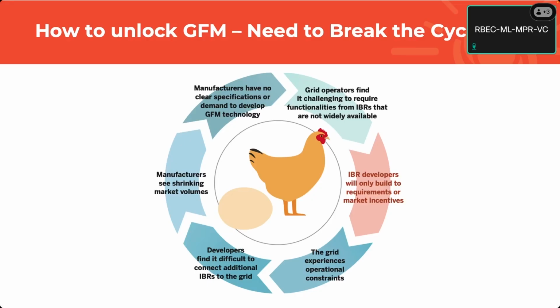Yeah. I think if you just have a regular inverter with a DC bus, there's no inherent problem with a grid forming control for the DC bus compared to grid following. It's going to be a current issue on the battery. You're not really cycling state of charge on a full battery. You're just moving the current in and out in a little bit different way. I'm told that it's not a problem for the batteries, but when you have a DC coupled hybrid system, now you have two different sources of current. That seems to be more challenging for DC control. I'm not sure exactly what the challenges are for them, but for some.